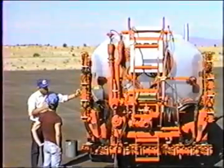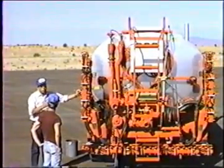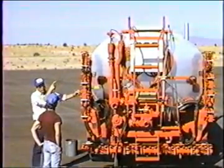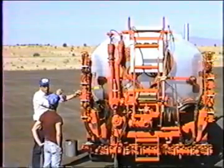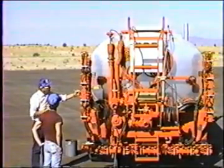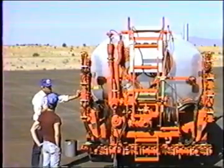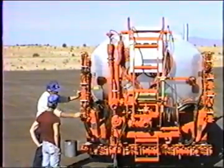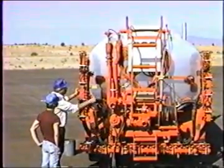The highest pressures that we're going to want you to ever spray at with the machine are around 12 or 15 pounds. 50 pounds of pressure on that is just to ensure that nothing goes back into the tank when we're spreading with it. We'll get a lot deeper into that when we get into spread rate and how the machine controls the spread rate.